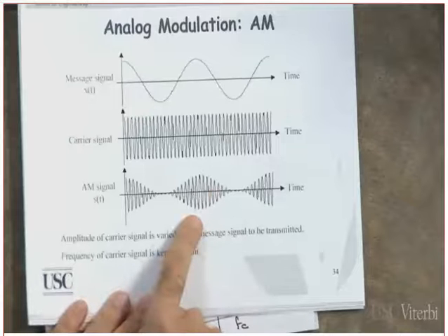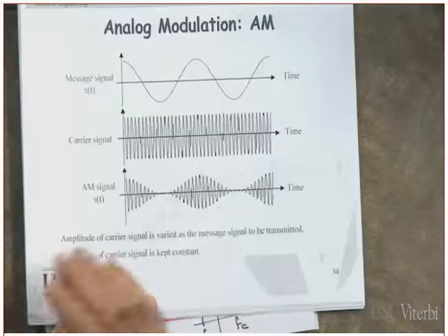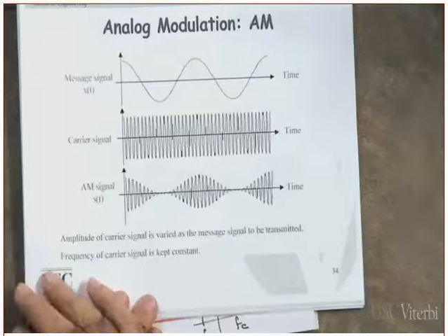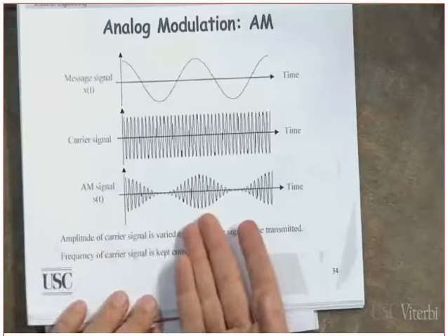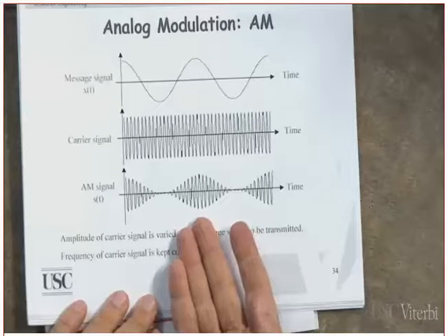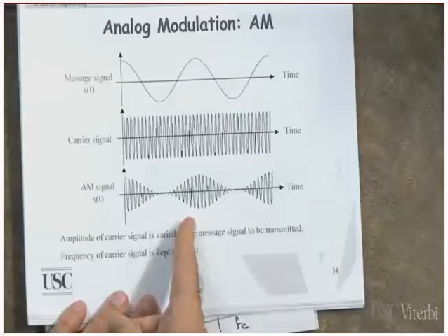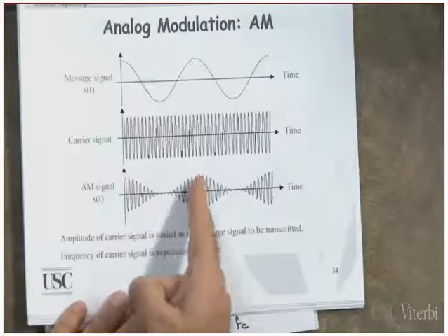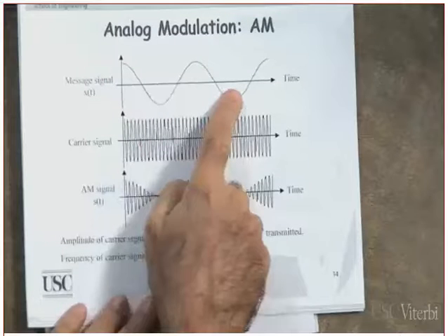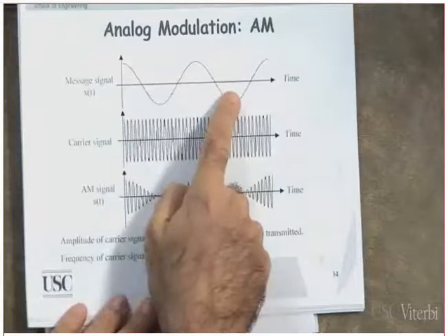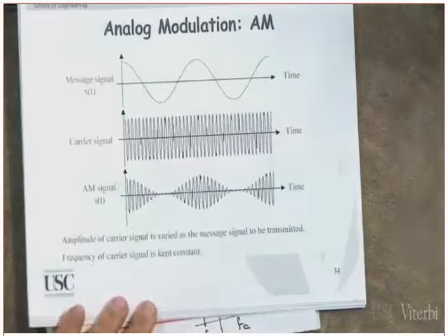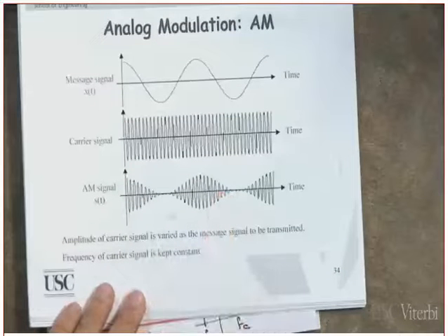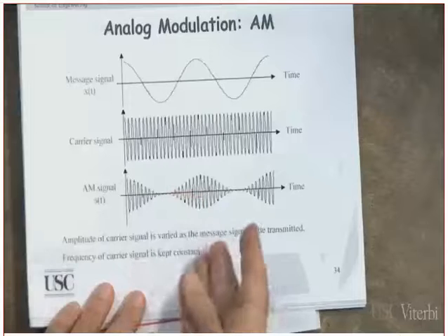Okay, tell me, what did I change here? I changed the amplitude. Are you following me on that? I changed the amplitude. You can see right away, this is a type of modulation which is called non-constant envelope. Is the envelope constant or non-constant? Non-constant. I want you to see the envelope. Does it follow the modulating signal? We will see that we can detect it, we can build a demodulator for this, a very simple envelope demodulator. Later on. But did you get the idea?